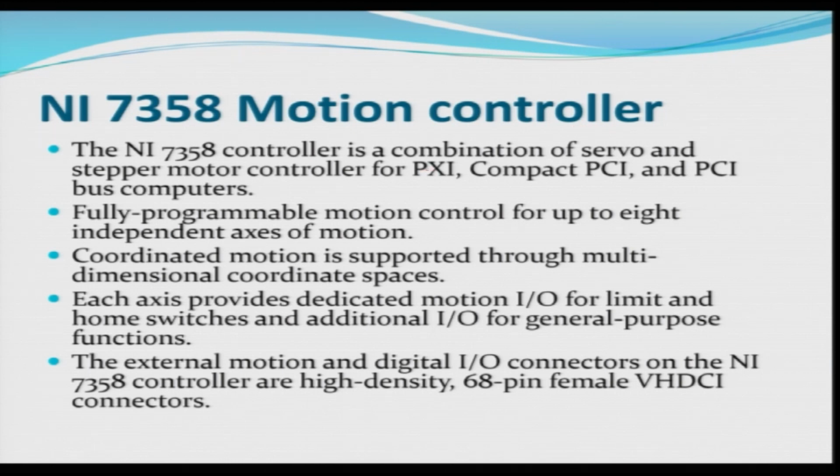This is a combination of servo and stepper motor controller for PXI, compact PCI and PCI bus computers. This is a fully programmable motion control for up to 8 independent axes of motion. Coordinated motion is supported through multi-dimensional coordinate spaces. Each axis provides dedicated motion I/O for limit and home switches, and additional I/O for general purpose functions is also available. The external motion and digital I/O connectors on the NI 7358 controller are high density 68 pin female VHDCI connectors.